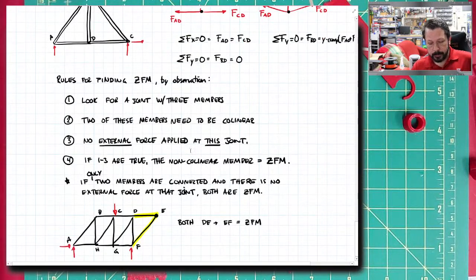Or we're looking at one particular loading scenario. This truss might have to be loaded a lot of different ways. And so under one scenario, there may be no force on those members, but under another scenario, there may be a force over there, and now suddenly they are carrying a load. So you have to remember that.